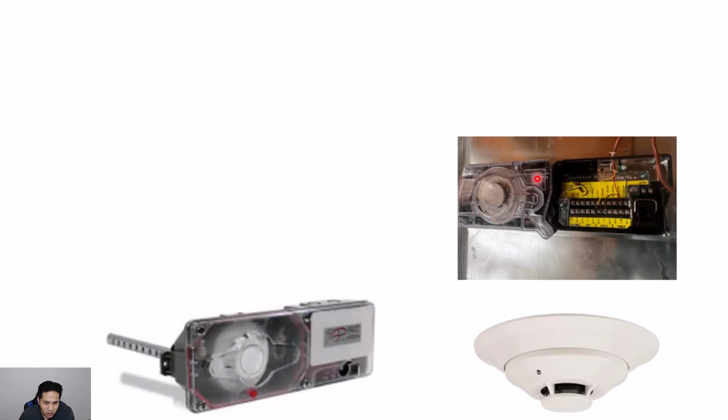So this is the container, and this smoke detector is actually mounted inside of this kind of plastic container. So as the smoke is passing through the duct system, it'll go into these nozzles, and then it would end up in this container, which would then set off the smoke detector. So this is what a duct smoke detector looks like.